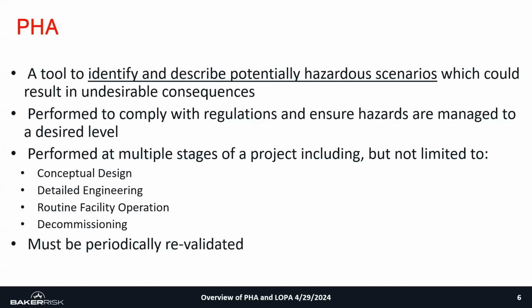PHAs can be performed at multiple stages of a project. For example, when you have a conceptual design, or even as that project progresses to detailed engineering, a PHA can and should be performed. But also, if you have an existing process, you can perform a PHA throughout that facility's life cycle, so during routine operation, or even at the end of the life cycle of that facility when you may be decommissioning it.